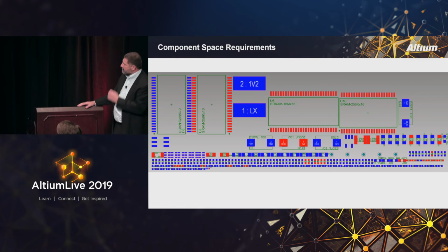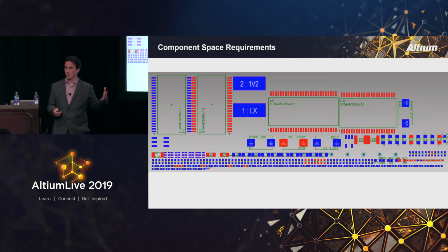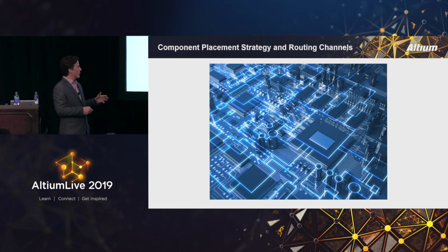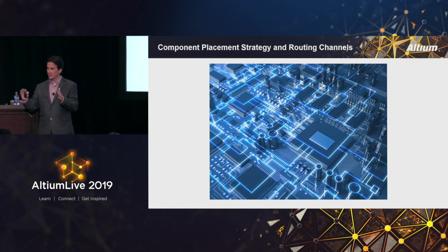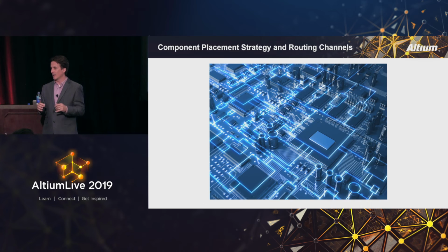I'll just say real quickly, it was interesting to hear that Carl and I had a very similar approach to that, and that we do the functional blocks first, and then I put the puzzle pieces together on the printed circuit board. But one of the things that I try to do, after I've placed those puzzle pieces together, is organize things in a systematic way. So I have banks of capacitors or resistors, as long as they're staying in the optimum position. I'm not doing some crazy scattering of parts on my circuit board.